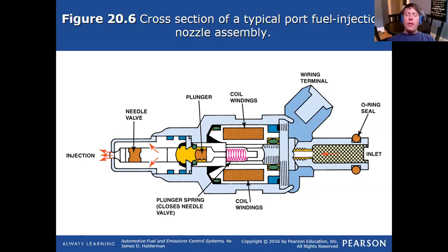It's a very, very, very fine filter. In theory, you should be able to drive that vehicle for hundreds of thousands of miles and never plug up those screens. But what happens is people don't change their inline filters, and for whatever reason, maybe the inline filter degrades because a lot of times they're just a paper element, and they allow bigger junk to pass through. And so that bigger junk will end up landing in these baskets and clog individual injectors.